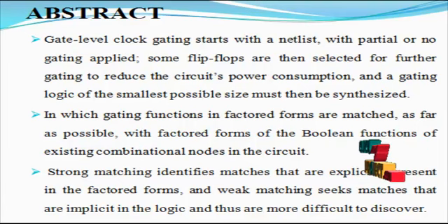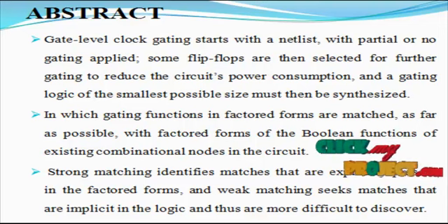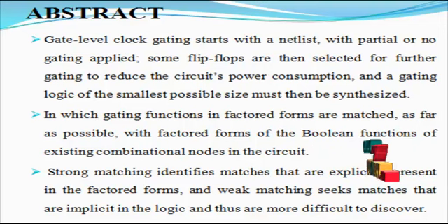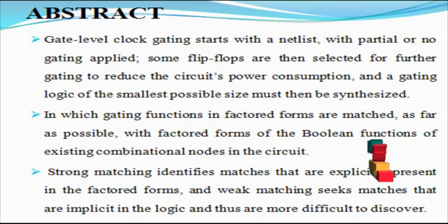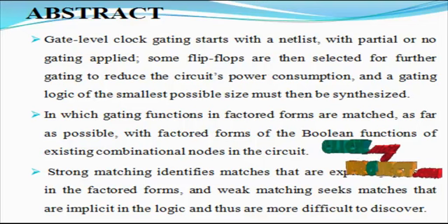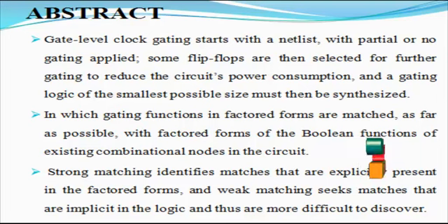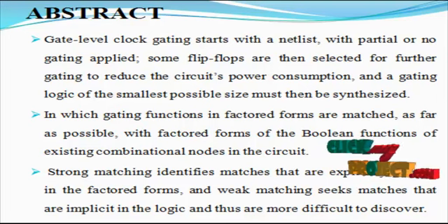It involves the conversion of load-enable registers to registers using clock gating. Clock gating is usually applied within the RTL design. During the process, a clock gate is inserted, which contains an internal latch that filters out potential glitches from the block called the gating function.